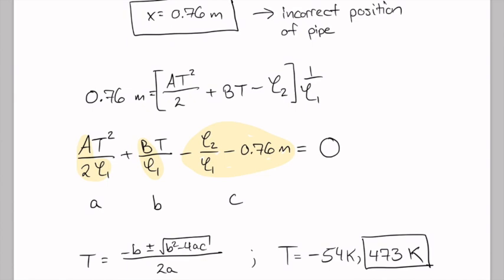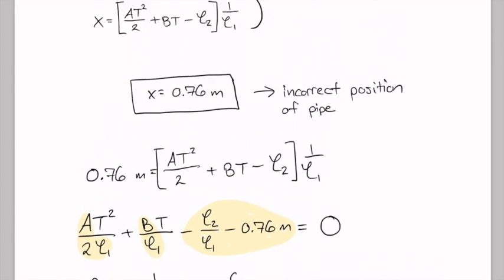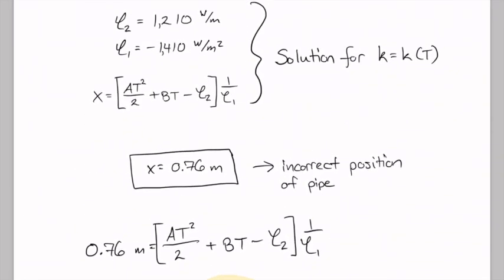We should also just take a look back on our original solution here and think about how accurate it is. Yes, we've written a very fancy expression for thermal conductivity, but we just kind of assumed that wherever we stuck the pipe in the wall, it was just going to be isothermal at whatever the wall temperature is. And that's probably not a very good assumption, because as soon as you put the pipe in the wall, you change the heat transfer profile around the pipe.